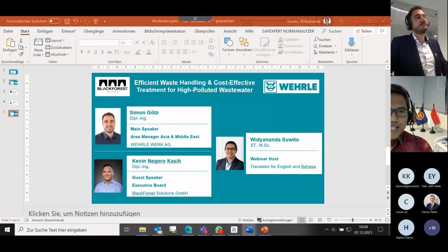Then to the next question, still related to the MBR biomembrane technology. The question is from Mr. or Mrs. Hang. Is the TKN oxidized totally into nitrate in the aerated tank as well? Exactly. This is one of the main jobs of the MBR or of the aeration tank.